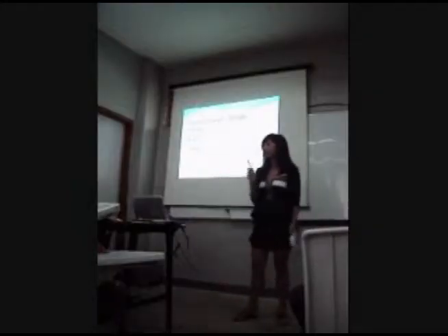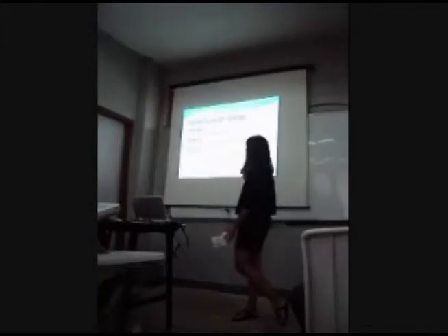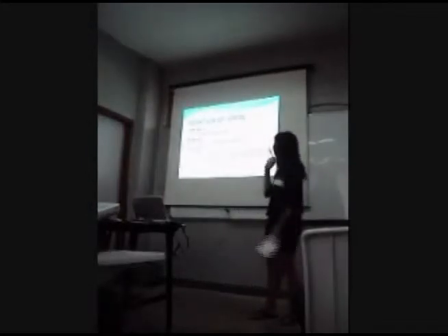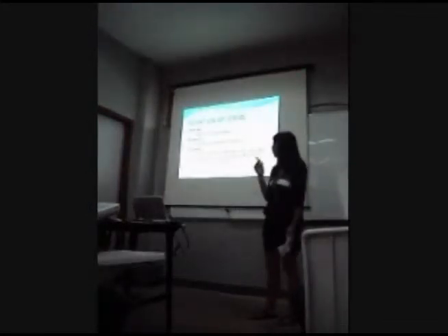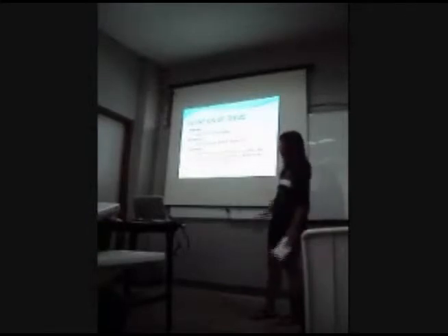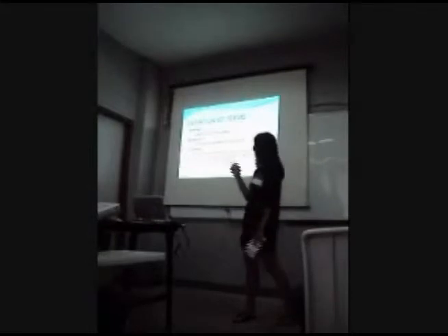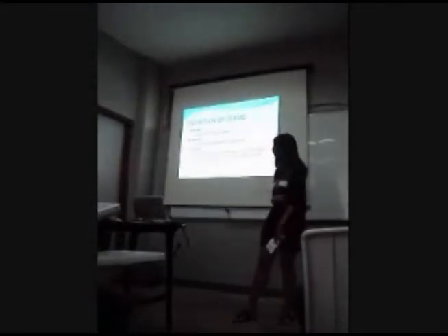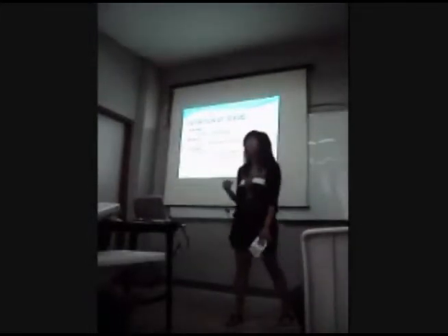Fouling, foaming, and flooding. Foaming is the formation of bubbles by the liquid. And then flooding is the condition when the liquid completely fills the void spaces in the packing and no more liquid flows down the tower.